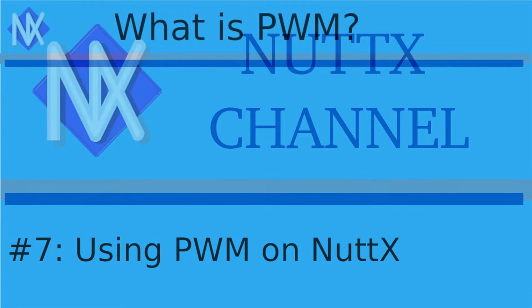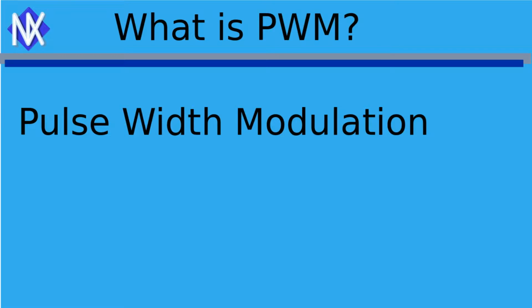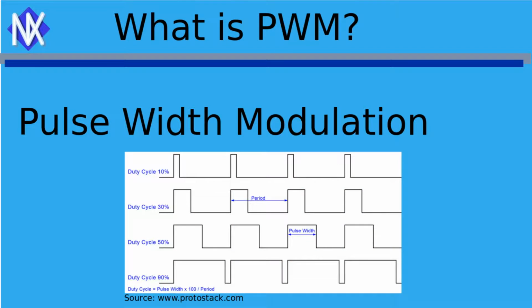Hi everyone, today I show how to use PWM on NuttX. PWM stands for Pulse Width Modulation. Basically you have a periodic pulse where you control the width of this pulse.